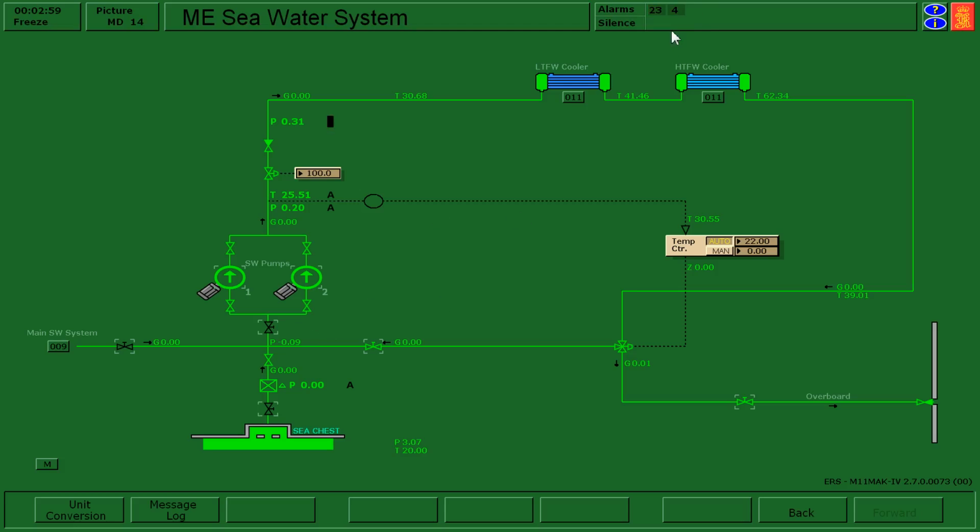Before we do, let's just take a look at some of the information that we've got in case we didn't know what the problem was. Well, first thing that we see is blinking on the screen. There's a blinking L. L signifies low. If it was blinking H, it would be a high alarm. This time it's low, and what it's telling us is the pressure is low.